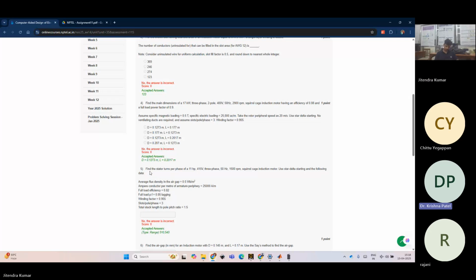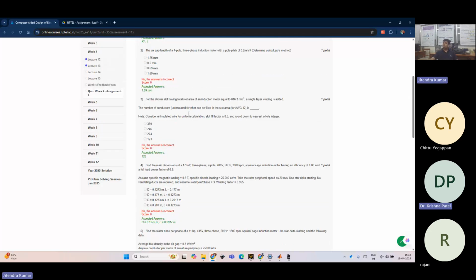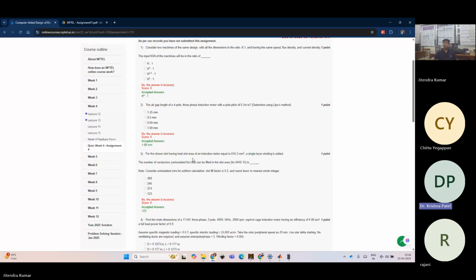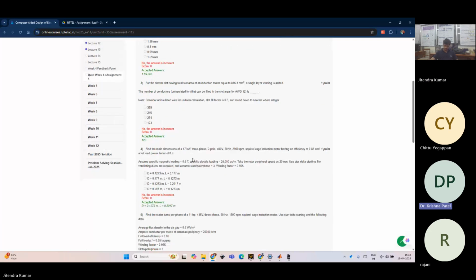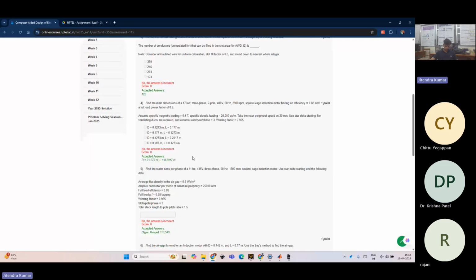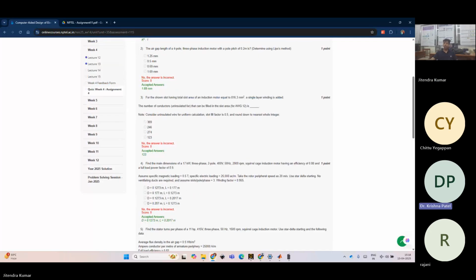Stator turns per phase, 247. Yes, right. And in this scrolling and cogging, we are not able to select both, we have to select any one. Yeah, I have noted both the things. And that question, alpha is 15, means x is 15-degree pitch factor. Yes.